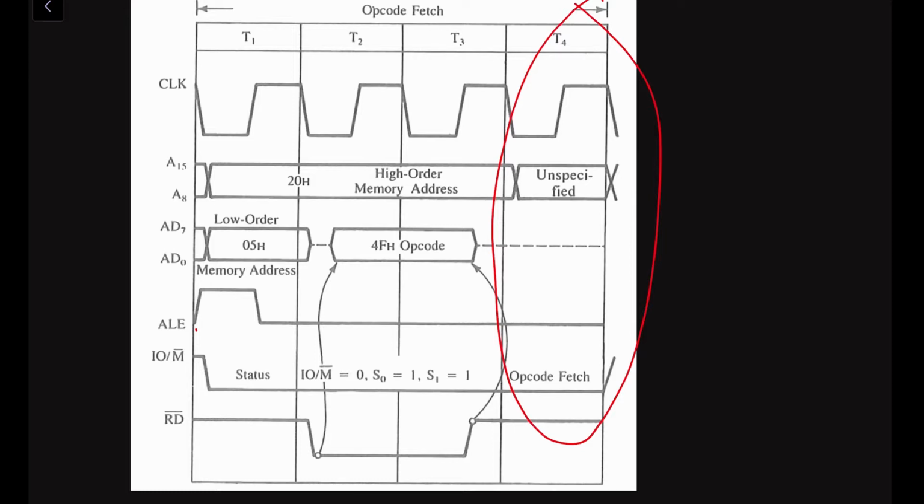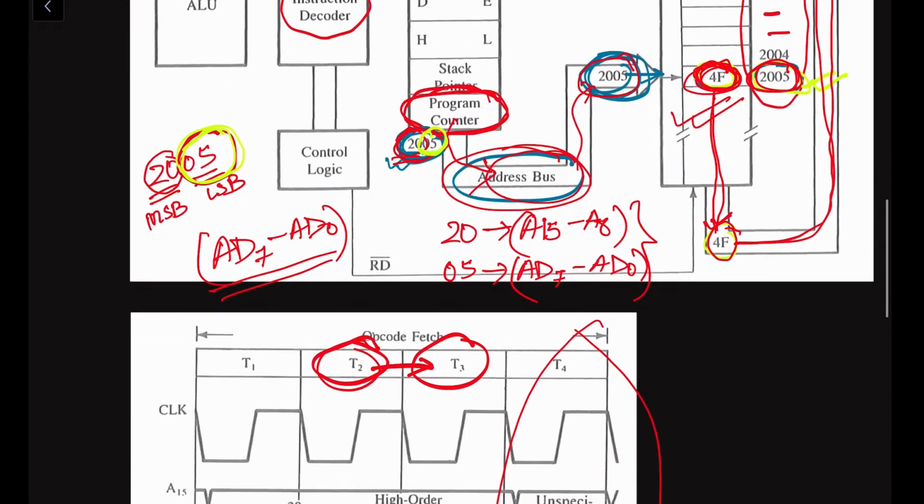and the microprocessor examines the READY signal in T2. During the T2 cycle the microprocessor finds whether it is ready or not to perform the operation. When it is high, the microprocessor enters T3. If it is low, the microprocessor inserts a wait state between T2 and T3. When it is low, it will wait. There is a wait cycle. I have already explained this in my previous videos, so watch all the previous videos and the upcoming videos also, then only you will understand. I have explained with the block diagram and the timing diagram.